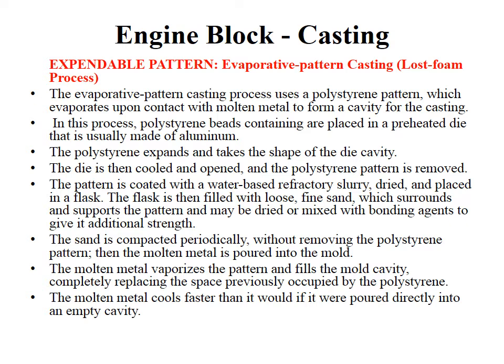So in the conventional methods where you have an empty cavity, if you pour it, it will take a longer time to cool, but if you pour it in this lost foam process, then the cooling process is faster.